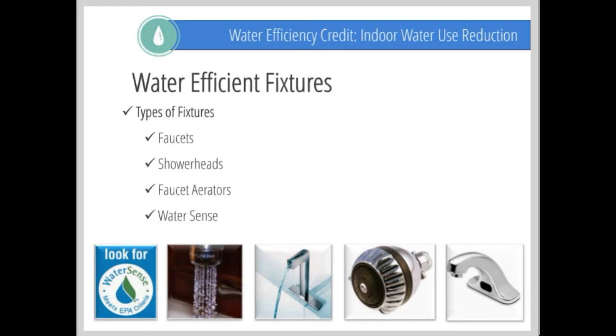Efficient faucets can help increase a building's water efficiency. There are also the reduced metered valve faucets that shut off after a designated amount of water is dispensed from the tap. This prevents user errors that can affect a building's water efficiency, such as someone who does not close the tap all the way and leaves the faucet to drip overnight.